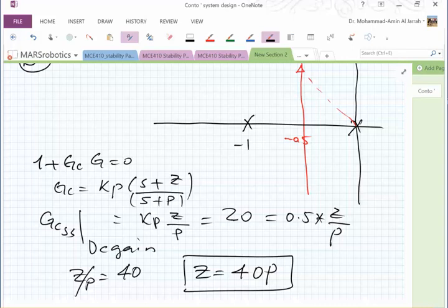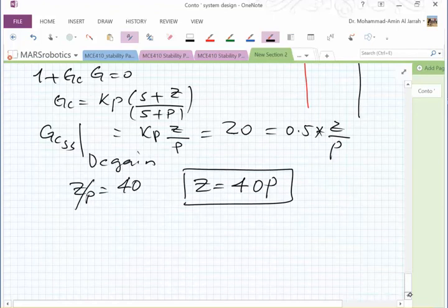Now, where are the problems? When we go to the implementation. Theoretically on paper we can do it. But when we go and implement it, when we start to select components, capacitors, resistors, etc., then we will face a problem. Sometimes you end up with a very small motor and a huge gearbox. You want a very large torque, so you can take a very small motor and a huge gearbox, and you get a very small RPM, but the torque is what you need. Now in terms of cost and availability, is this the best solution? No, you have to match impedance.